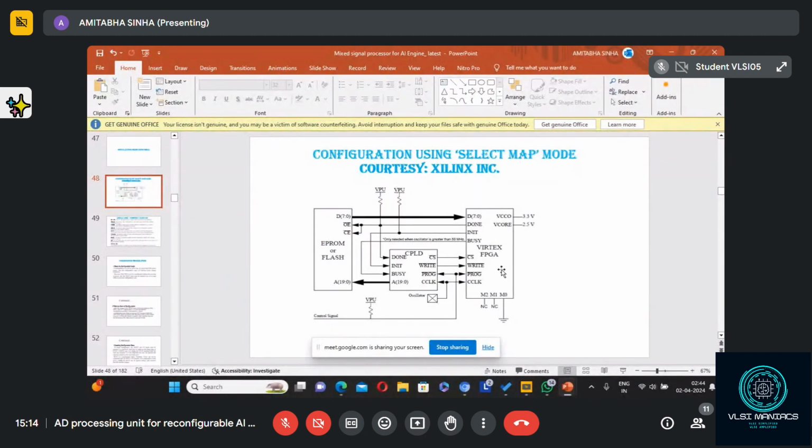You require a write signal, the chip has to be selected, and data in the data bus. If the data are stored in consecutive locations, then there is no need for an address bus. Inside there will be a counter. The counter will be initially reset to location 0, and then one by one the data will be stored and the counter will be incremented each time after storing each data. That's right.